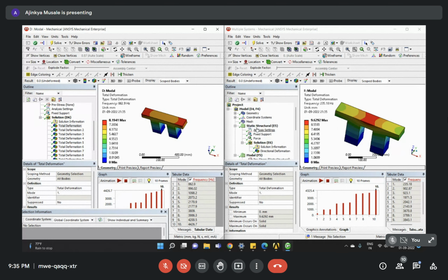Why is it actually necessary? If you are having this kind of bridge, and you are thinking of applying some weight in the middle of your bridge, maybe putting some structure at this end, or maybe a statue, it will have its own self weight. Because of the addition of some load, it is in a pre-stressed condition. So it is already having some load, and it will have different natural frequencies than it has without any load.